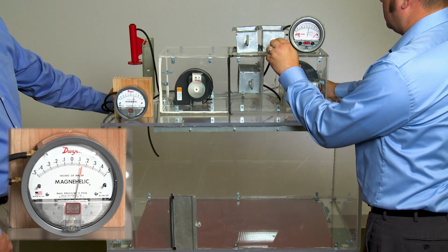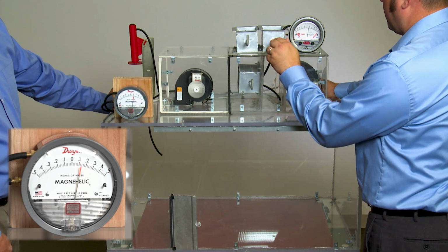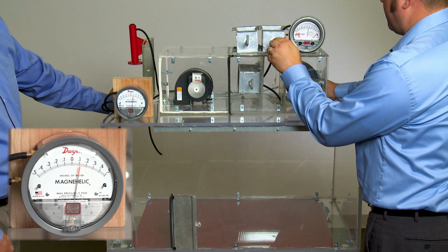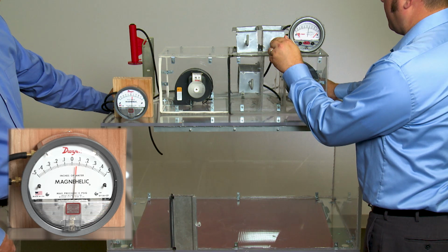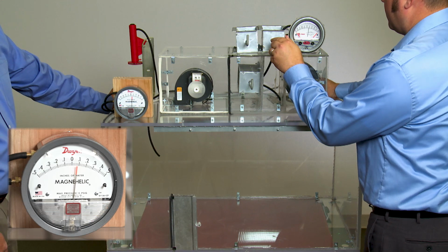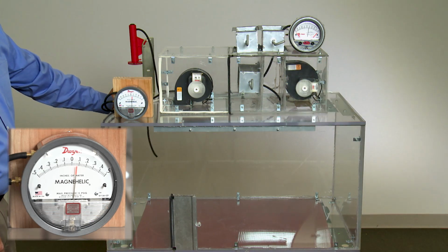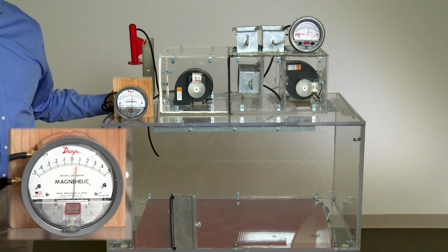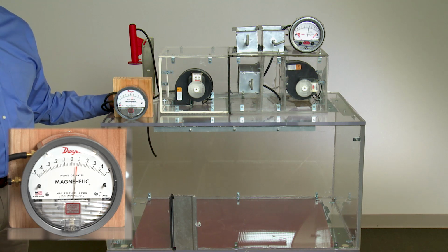Changing the position of the relief damper and the speed of the return fan at the same time both cause building pressure to change. So Eric and I have our hands full finding the right balance point to settle out. This is why control of a return fan in a VAV system gets more complicated, because it requires proper tuning of these interacting control loops.